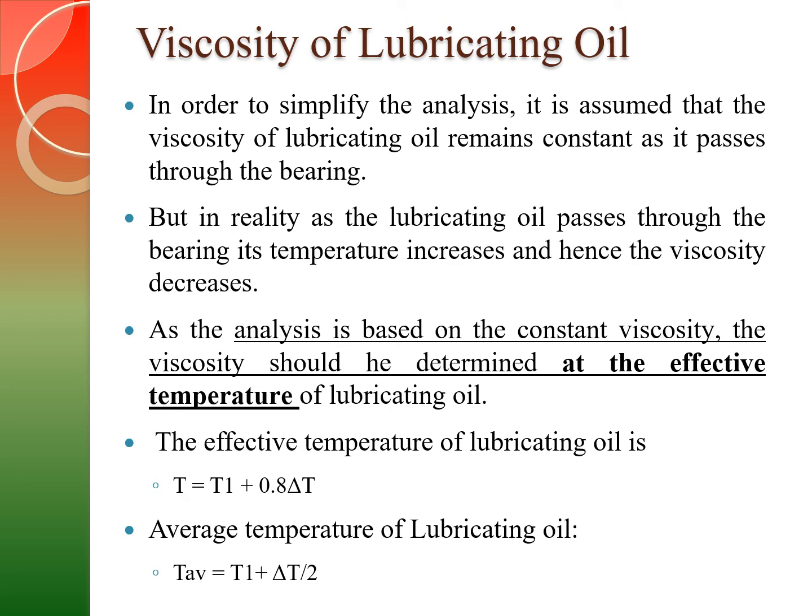So the effective temperature of the lubricating oil is given by T is equal to T1 plus 0.8 delta T, and average temperature T average is equal to T1 plus delta T by 2. Thank you for listening.